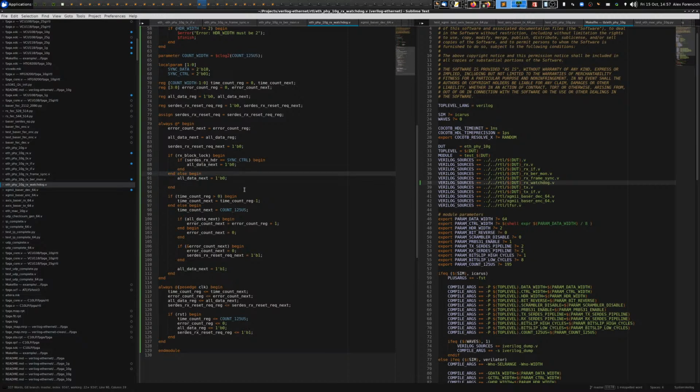The issue is I'm also thinking about some of the research that we're going to be doing, and potentially we're going to be breaking the links every 100 microseconds or so, and that is going to cause block lock to go low. So I think that condition is going to be a little bit too extreme. Well, so to get block lock set, you have to see 64 sequential blocks.